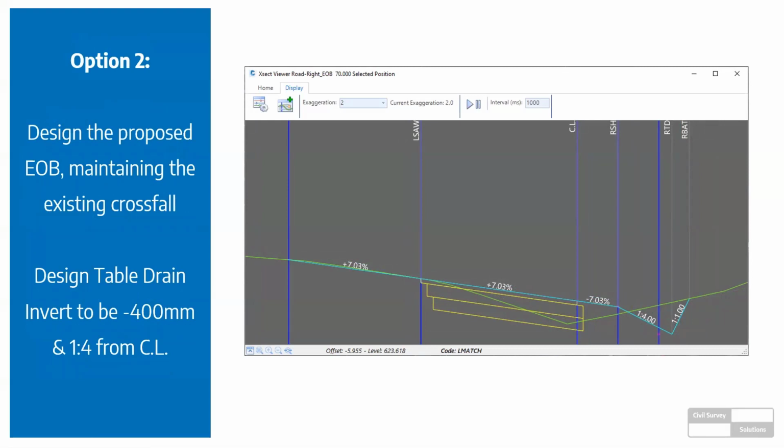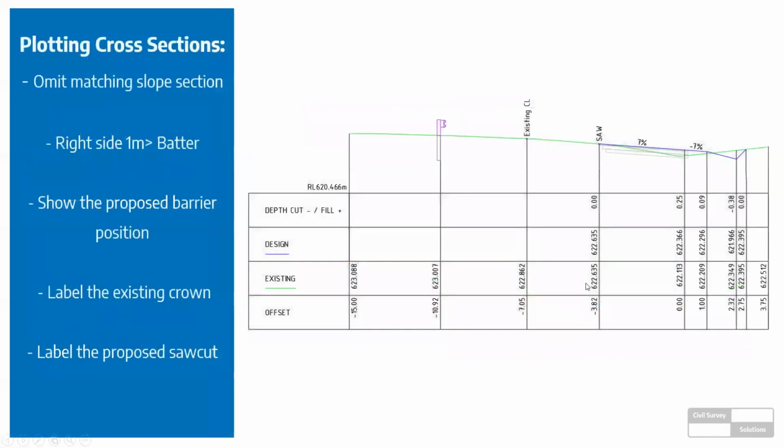In this case, the point of control, or the start, or the center of our design is actually going to be along the edge of bitumen. And we'll talk about this in a second, but we're actually going to be designing along the edge of bitumen and then putting codes out to the left and then codes out to the right. So a different approach, and there could be good reason for this. Before I go on to that, let's just look at the final part.